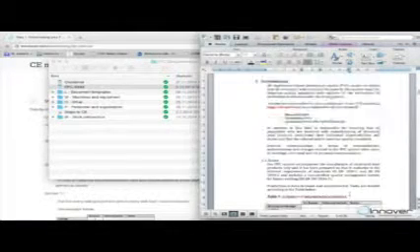But usually what we have done is that if the subcontractor is not going to CE mark the product, they're just going to mention it here. And if, for example, we are buying preparation for surface treatment from outside and they are able to CE mark their product, so they have a valid 1090 in place, we're just going to leave the notes empty. So this is the next step. So fill out the table 1 for the in-house resources and subcontracted products.